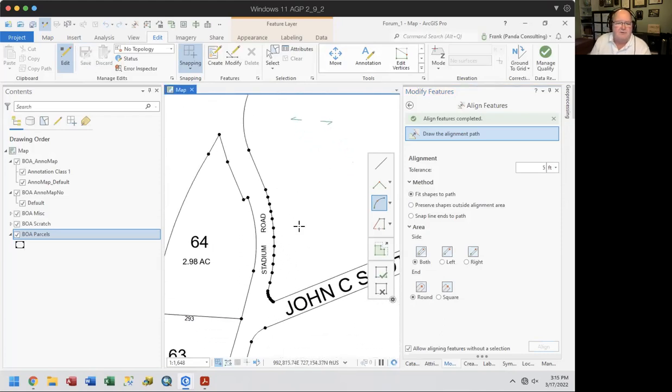So that's one of the other tools you want to look at when you're making this transition from ArcMap into Pro. What do I need to think about? You want to make sure that you've handled your Anno and your COGO. Look at vertices and clean up that data. Make sure you have coincidence between these lines and not gaps and overlaps, especially between different layers.